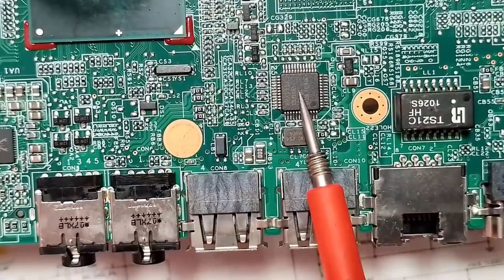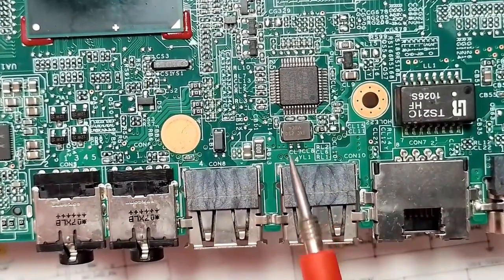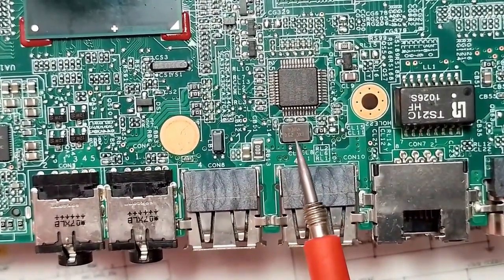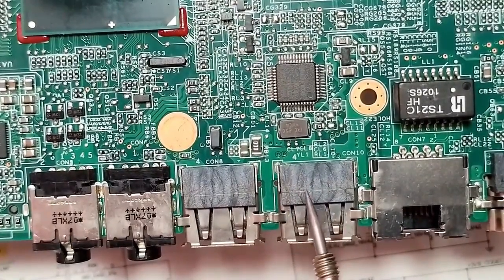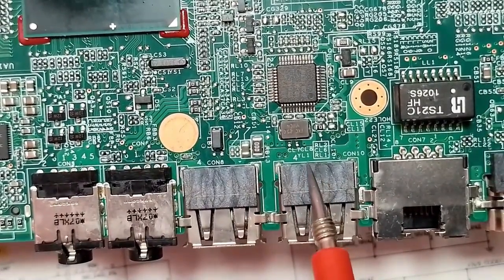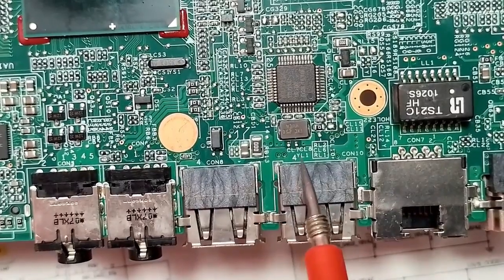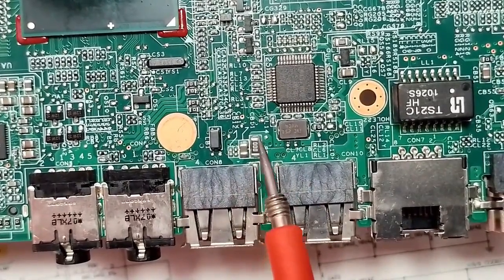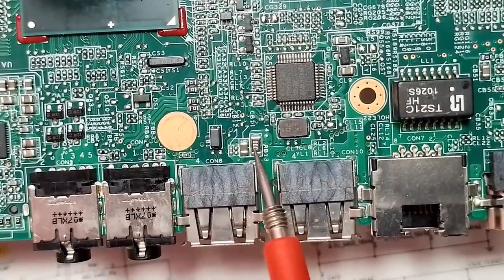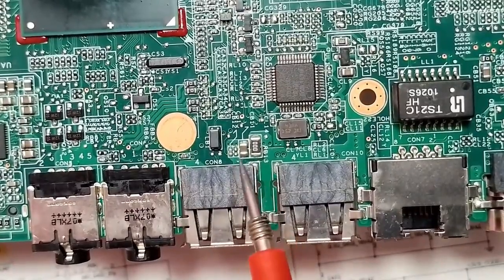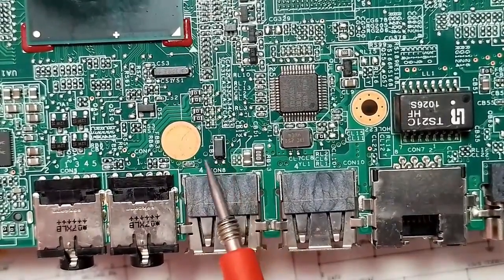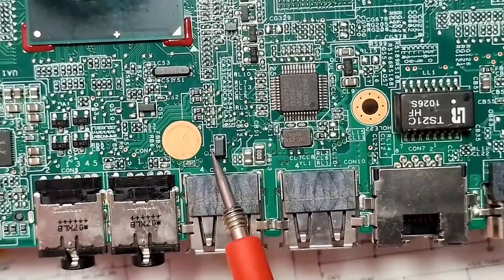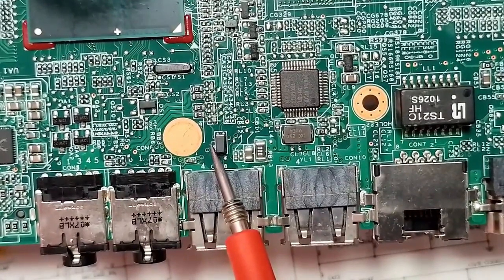So this is an integrated circuit. Here we have a crystal oscillator. You will always find its reference is X or Y. As you can see here, we have Y. This is the resistor. 3 zeros means this is a fused resistor. Here we have a ceramic capacitor. Here we have an inductor. We have L. Always L refers to an inductor or coil.